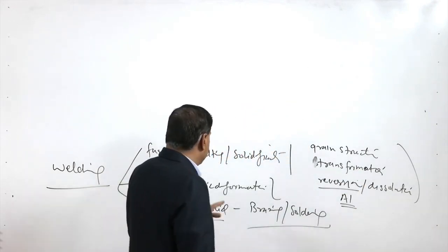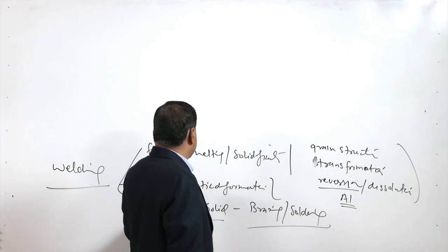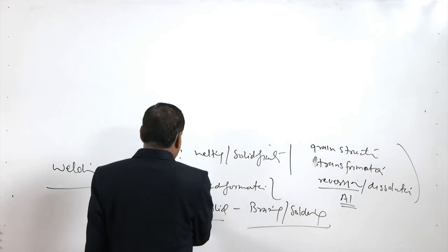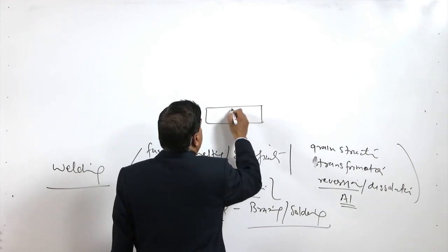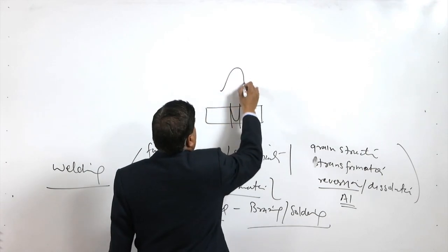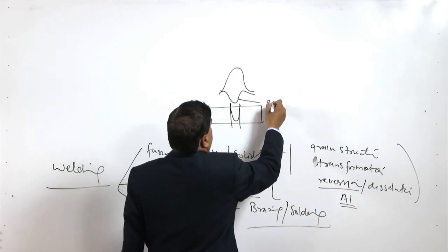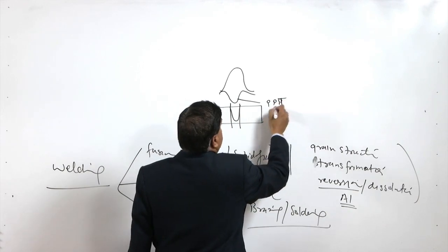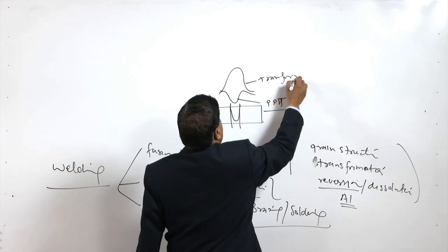So, depending upon the kind of metal systems, the plastically deformed, that is, solid state joining process may lead to the development of a weld wherein the nugget area may offer much higher hardness or it may lower the hardness. This is true for the precipitation hardenable systems, and this is for transformation hardenable systems.